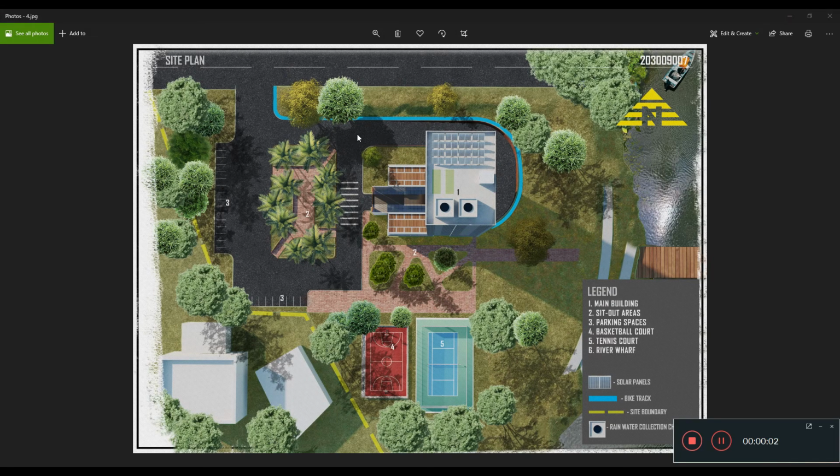This is the site plan of the project, and as you can see, because it is for a tropical climate, there's a rule for the building orientation. It is advisable in the tropical climate to orientate the longest part of the building along the north and south direction of the site. So I've done just that because doing this will allow you to have more daylight coming into your building while avoiding the direct impact of the sun rays as it travels from the east to the west.